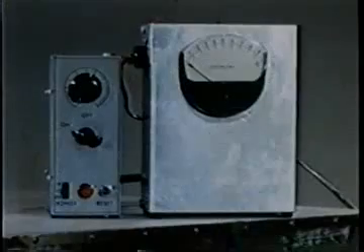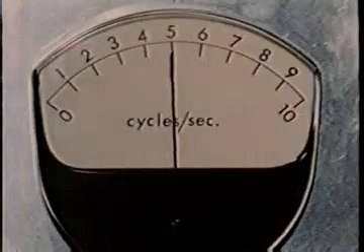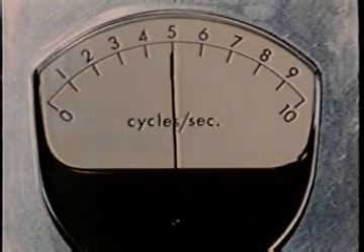In order to find the frequency response of amplification, we put in sinusoidal disturbances which we can control. We start the wave maker oscillating at 5 cycles per second, at 0 airspeed, and see the waves damp as they travel away from the wave maker. With the tunnel running, but below critical airspeed, we don't notice much change in wave damping. As we increase the airspeed and pass critical speed, we see the waves grow.